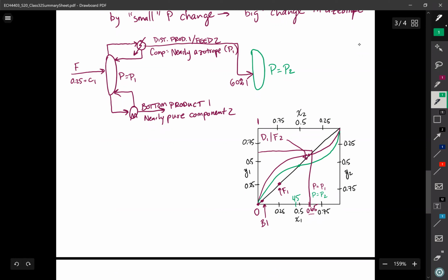All right, so that's going to allow me to jump the azeotrope. I'm now in the regime where component 1 is going to be the less volatile thing. And from here, I can design the second column as I typically would do. The only confusing part is that now my equilibrium data is below the line. So how do we treat that?